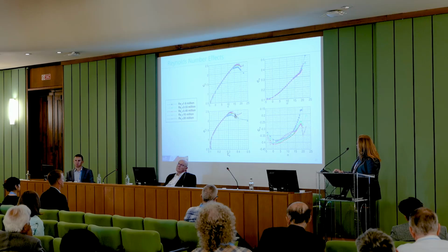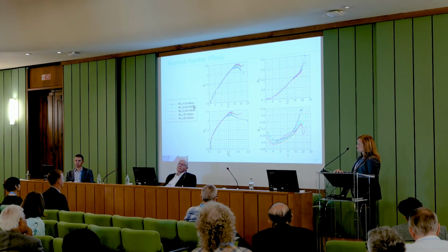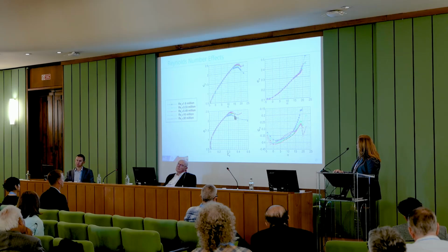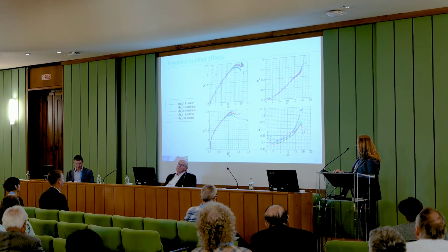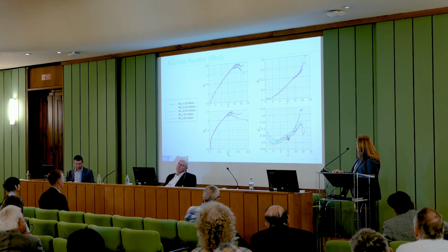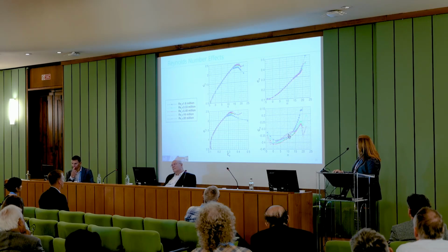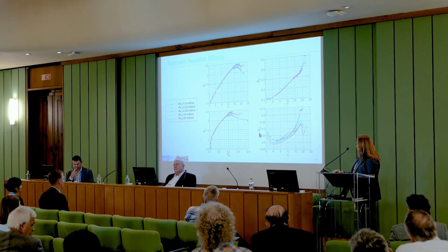Okay, and then we were able to look at the Reynolds number effects. We tested from 1.6 million up to 30 million. And as you can see, as we go up in Reynolds numbers, the lift does increase. There's something going on with the pitching moment over here as we increase in Reynolds number, but we haven't dug into that yet.